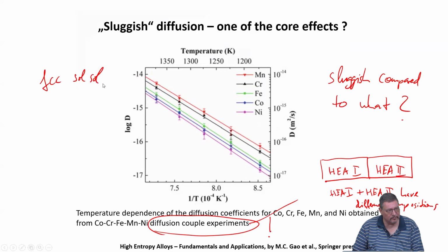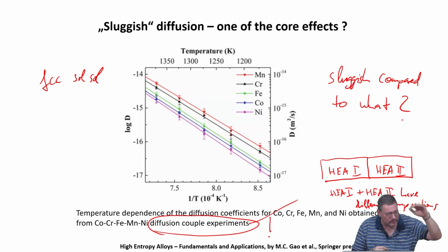If we change the crystal structure, it will be much different, yes. What would you think? It will change, because a BCC element will not go easily in FCC. But the nice thing about the Cantor alloy is we have several elements in there which are not FCC, but the whole thing at sufficiently high temperatures is completely FCC. At room temperature, it is different.